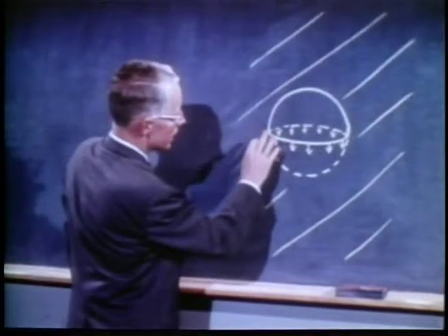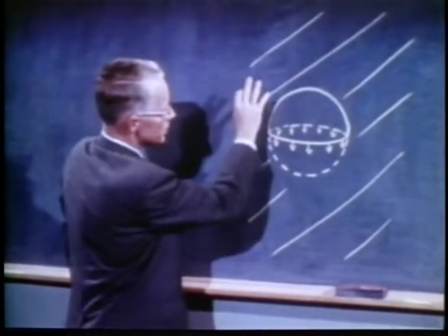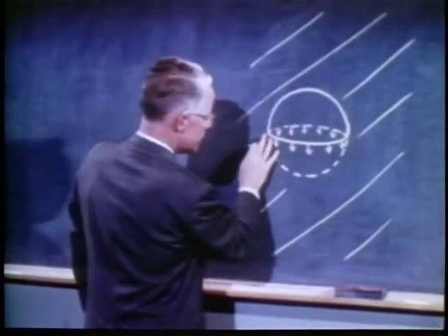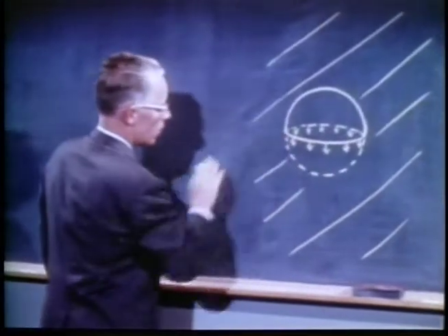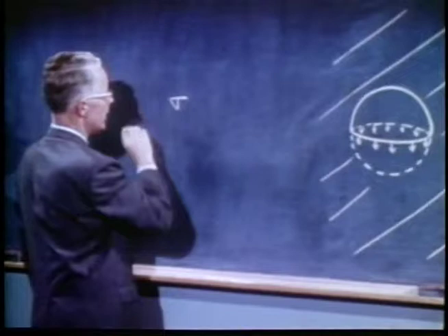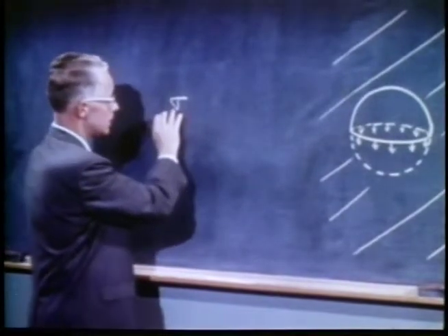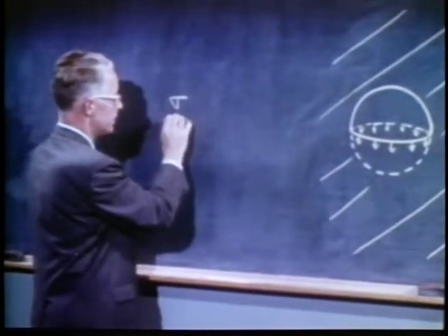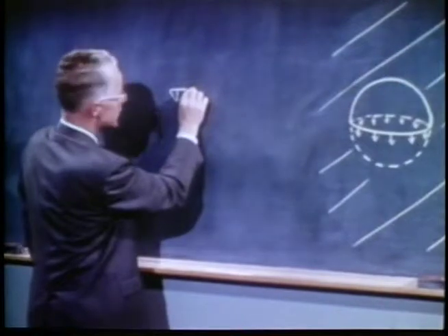Consider the upper half of a gas bubble immersed in a liquid. Surface tension will pull down all around the equator with the total force equaling the surface tension expressed as force per unit length times the length of the circumference.